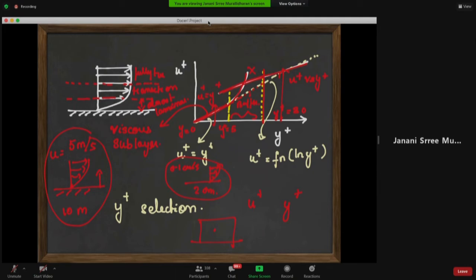So we have understood that for good predictions, you need to capture the velocity profile at the wall accurately. This is more difficult in a turbulence case because there are a lot of circulations involved and the velocity profile has three regions through which it transitions.